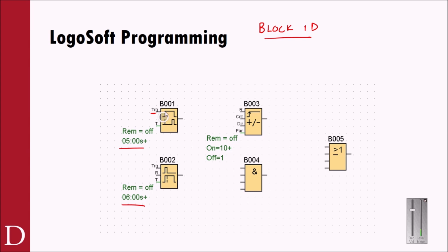If the trigger goes high right here, it looks to me like that starts a timer timing, and I'll call this time T in here. And then I delay turning something on. That's that time T. Well, this would be an on delay timer, TON or on delay timer. You'll notice this one, when the trigger goes high, the output turns on immediately. But when the trigger goes low, that's when I start timing. There's your dashes again, and I wait to turn off the output. Well, this would be your TOF or your off delay timer. Very important for you to at least recognize the difference between those two timers.